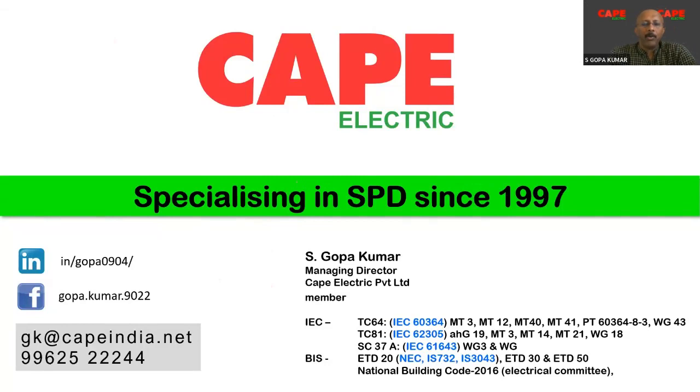The SPDs are connected in parallel to the circuit. As a result, in case of any failure in your SPD, the installed site is going to have a problem. So in comparison to other protective devices such as fuses and MCBs, selection of SPD is very critical, because this device is connected in parallel, and number 2, at the end of its life this device is going to create a short circuit.